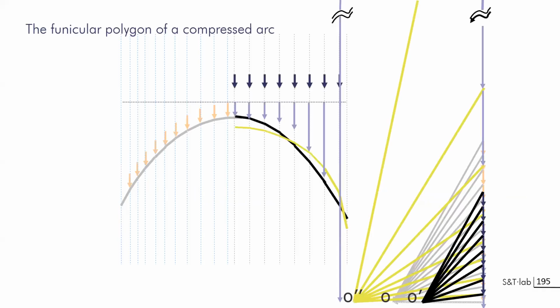You know that you can use the 2 tools we have. On one side, on the left, you have the space diagram, and on the right, you have the force polygon. So you can go from the geometry, so from the space diagram, to the force polygon, or you can go from the force polygon to the geometry. Going from the force polygon to geometry is form finding, and in the other sense, going from the geometry to the force polygon will help you to have the information about what could be the loading you are using on a structure. Here you have 3 different geometries.